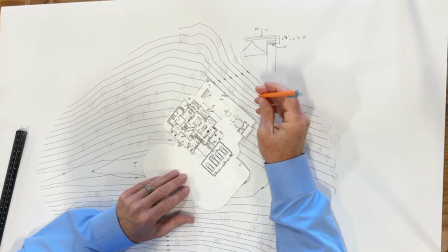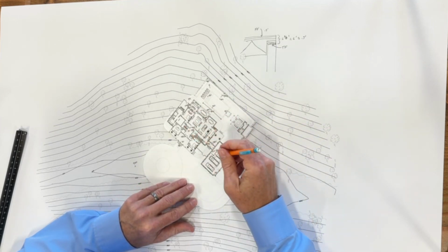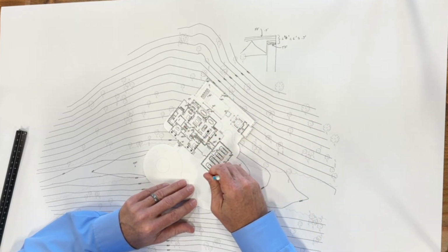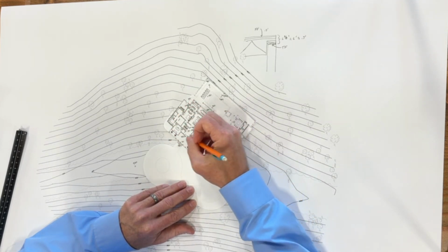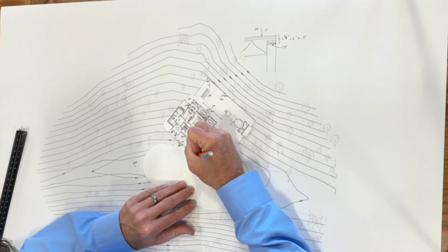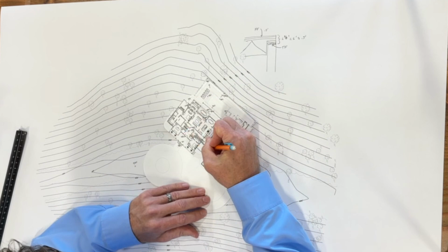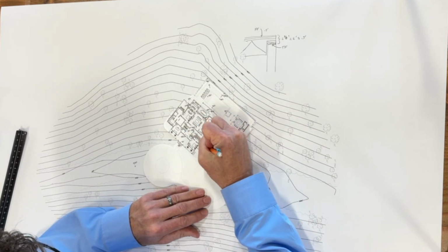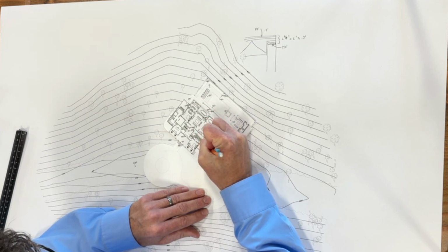So, okay. So now what we want to do is start drawing contours. So the 941 is actually on this line right here. And we know it comes through right under the deck as well. So that means here's your 941. That basically, well, actually, let's see. That'll have to drop a little bit. So you have a door right here going out to the front. So a couple step downs there. So let's, in fact, probably just want to do one step. So we'll do a 941.5.